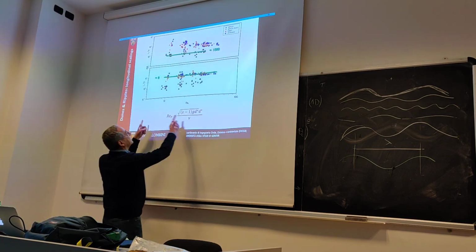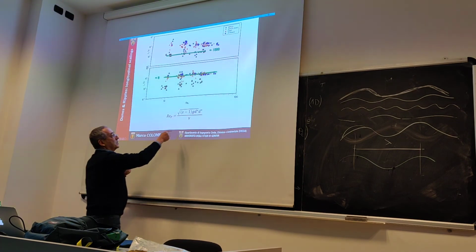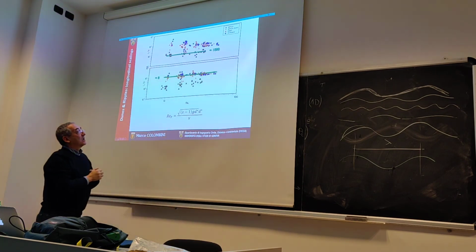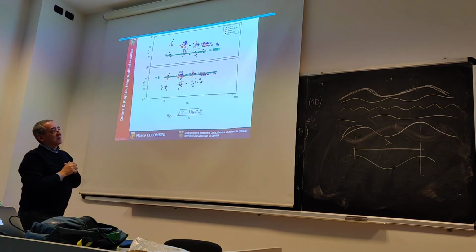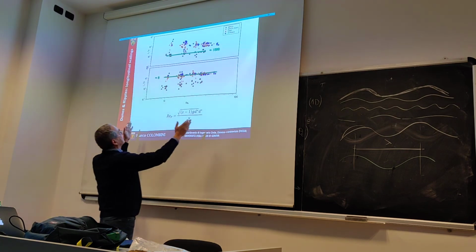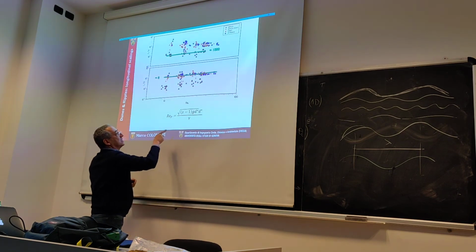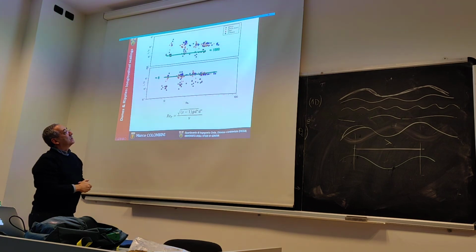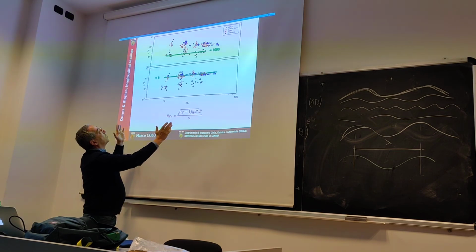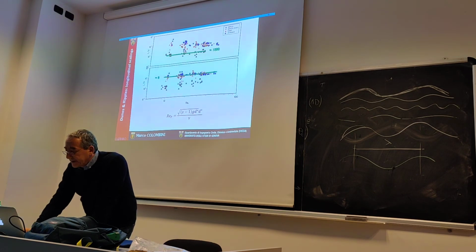And there is also another parameter that you can build up, like a Reynolds number, built with the grain diameter. This is the so-called particle Reynolds number. You can see that in a range of this, essentially coarser material and finer material, in a relatively wide range, the scaling applies much better.